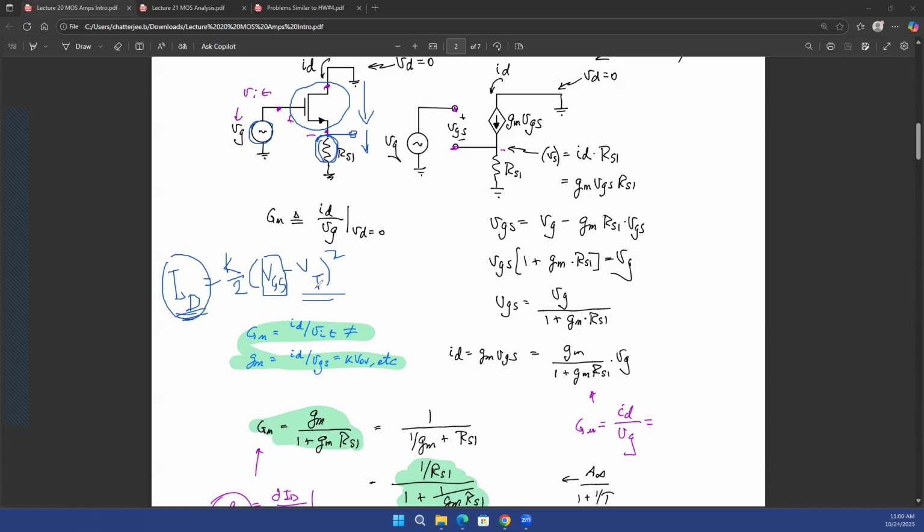So what did we get here? This is very interesting: if my VT went up, and I have this source resistance connected here, my VGS will also go up. And that will compensate for any kind of fluctuation in the threshold voltage. Question? It will almost equally compensate.